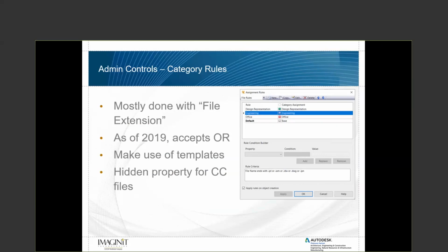One reason why Content Center files might want to be categorized separately is that a lot of them are static. They're read-only, you know, quarter 20 bolts, right? There's not much to them. And so some customers will create a life cycle and a category that automatically will release them, right? Because we're not checking them. A quarter 20 bolt is a quarter 20 bolt is a quarter 20 bolt. So by being able to identify a Content Center file and automatically releasing it, again, we're saving steps from having the users go through the steps of releasing them.